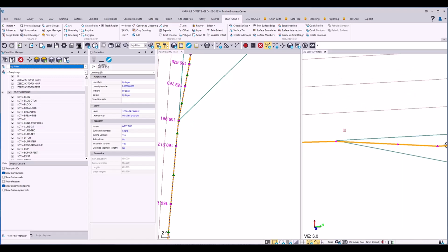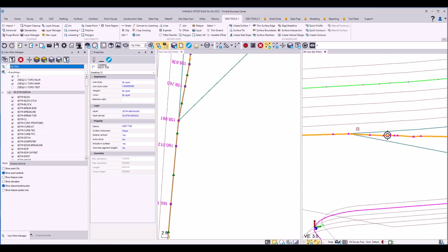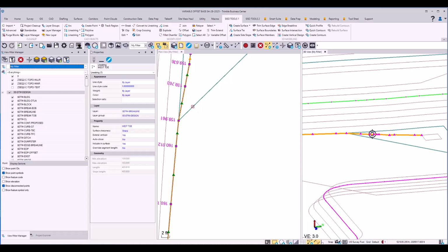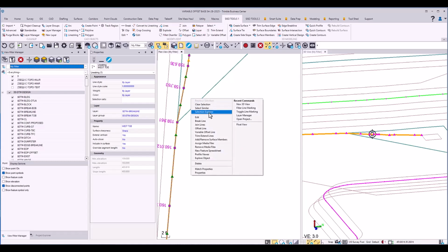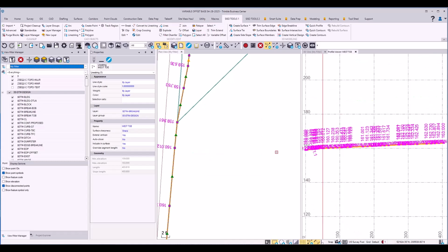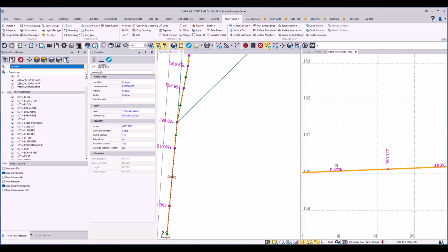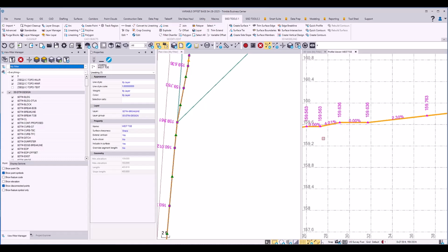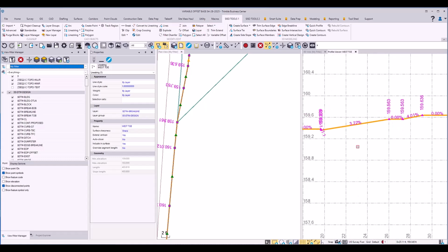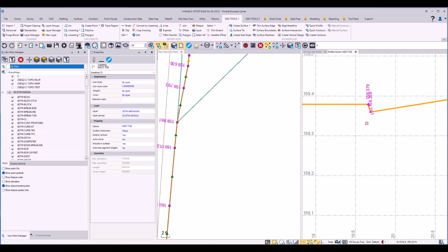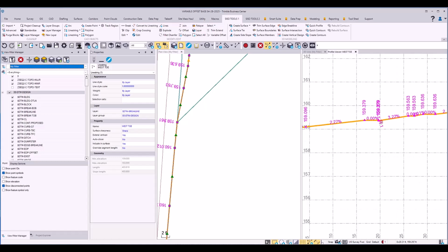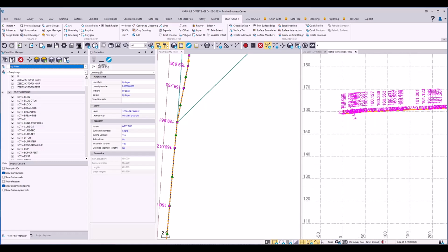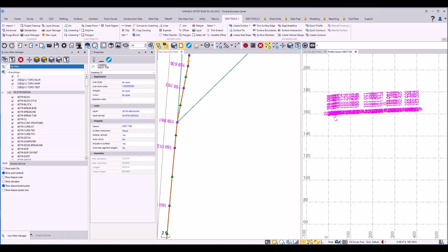You may say, what's a foot amongst friends? But that line looks squirrely as well. So let's take a quick look at the profile of this line. And if we zoom in on this guy, all sorts of stuff is going on here. It's going flat, it's going up at 4%, 2%, 0, and it's even going almost vertically down at some location. And for me, that's unacceptable, and this is the good, the bad, and the ugly of using